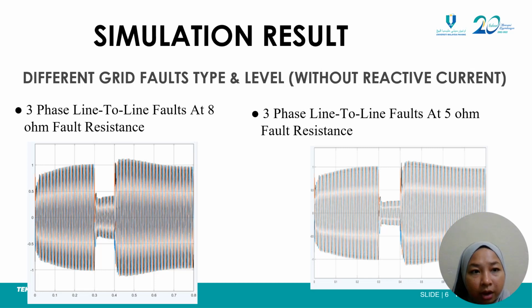The fault impedance is significantly lower than the system nominal operating impedance. Consequently, a substantial fault current travels through the fault phases, and the voltage reduction happens as a result of the considerable fault current increase, and the voltage division effect across the fault and system impedance. Depending on the setup, fault location, and fault impedance characteristic, the voltage drop precise magnitude may change.